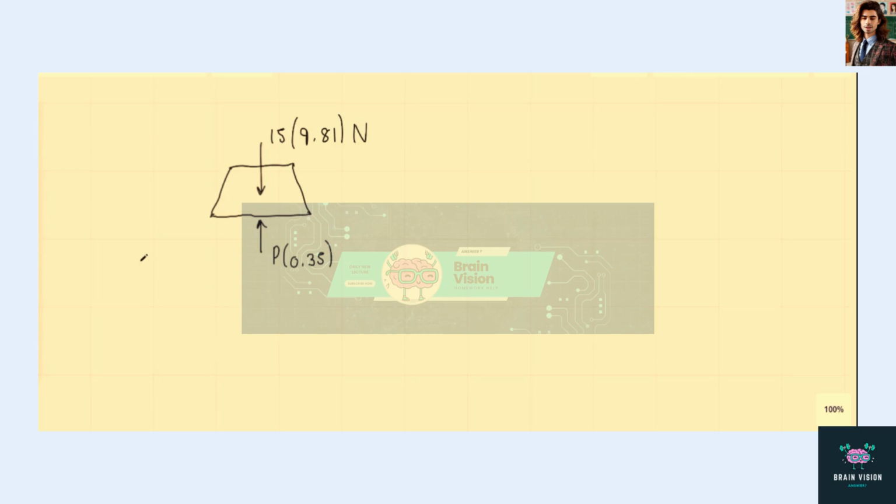In this problem, we have a mower which hovers very close to the ground, and this is done by drawing in air at a given speed through a given intake. The air is then discharged at the ground through a different cross-sectional area. We want to calculate the air pressure which the lawnmower exerts on the ground, when the weight of the mower is freely supported.